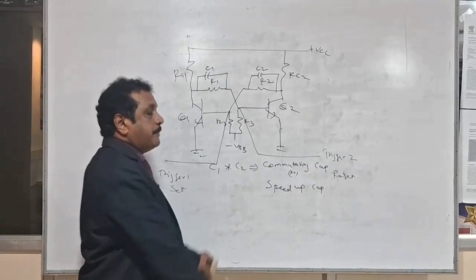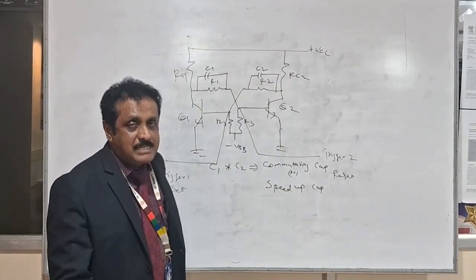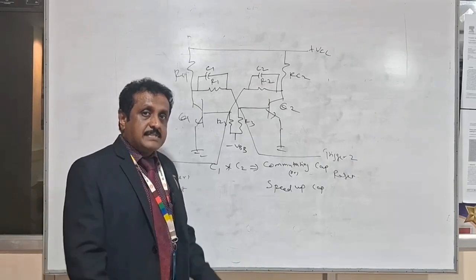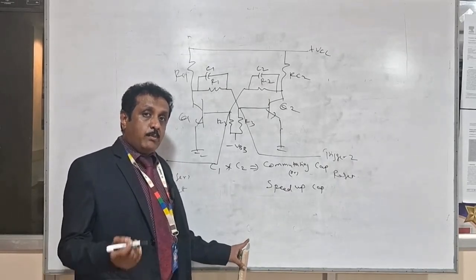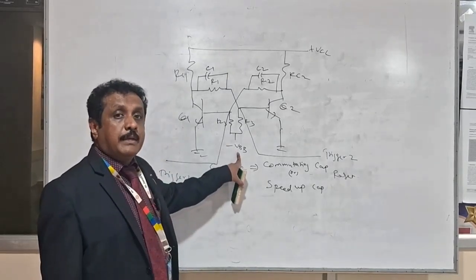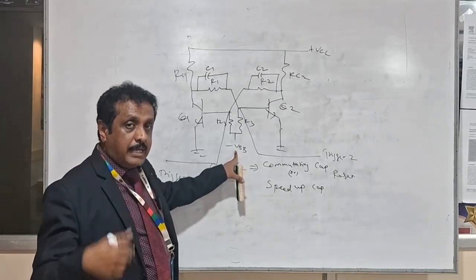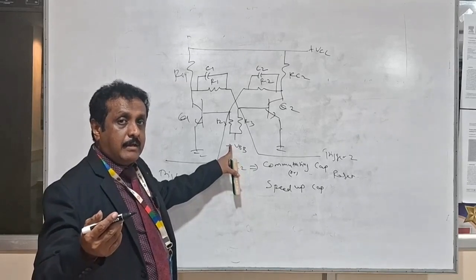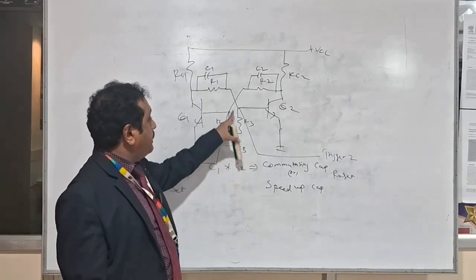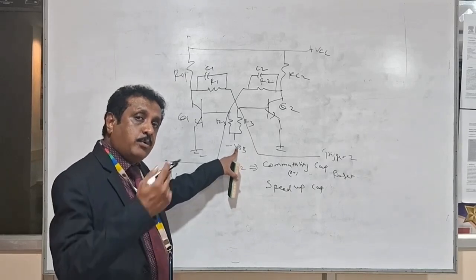Right. Now we are coming to the working. When the supply is given, due to some imbalance of the circuit, like astable, the initial state we can't predict. Any one of the transistors will be driven on, because both the bases are connected to minus VBB. But in monostable, one transistor base is connected to minus VBB. That's why we could say the stable state when it starts working. But here, both the bases are connected to minus VBB. Again, its initial operation is similar to astable mode.